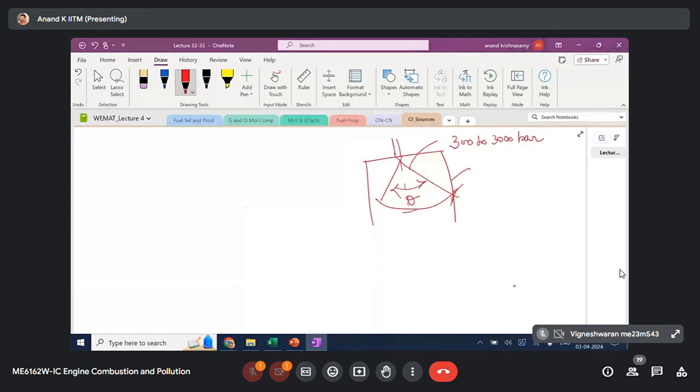Wall. You know, this is a cylinder wall region. You are circulating coolant here. So this is the region with the lowest temperature in the combustion chamber. So the temperature here is considerably low. When the fuel goes and hits the wall, it will form a film. So this is the fuel film. You will get a fuel film forming around the wall region.